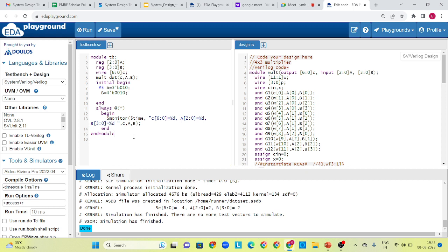Next we have the circuit. Ma'am, for the test bench, while applying our inputs, we are using a delay time, right? We can use different delay times, or do we have to use the same delay time for all the inputs? No, it is our wish. If we have some flip-flop, then practically we need different delays, and setup time and hold time we have to take care of, meaning we have to have constraints.